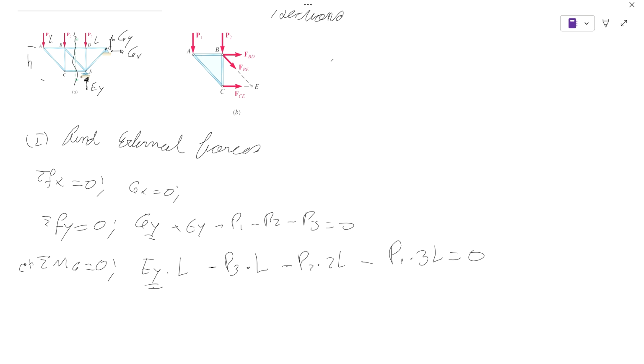So having the external forces, we can go into the components and say we're wanting to find the forces across, if B, the force from B to D and the force from C to E, or any other element in here. So we cut the section, which we can only cut up to 3 elements. So that's the restriction right here. We can only cut 3 elements.